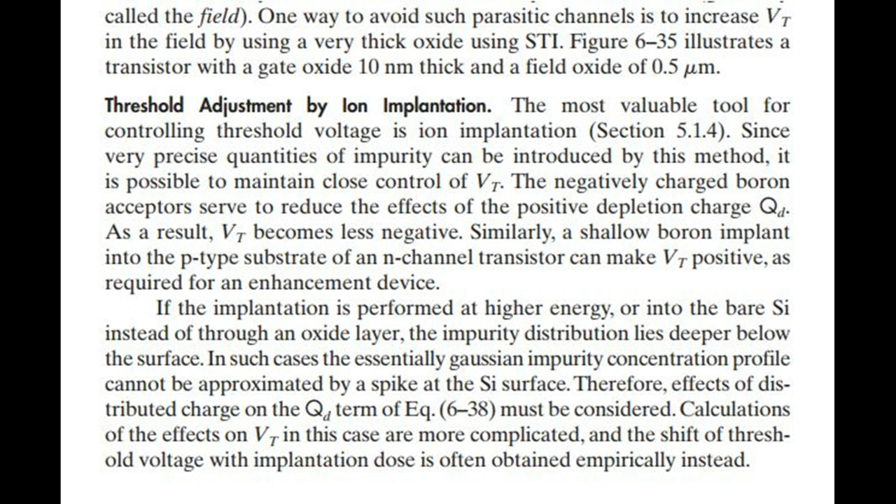In such cases, the essentially Gaussian impurity concentration profile cannot be approximated by a spike at the Si surface. Therefore, effects of distributed charge on the QD term of EQ 638 must be considered. Calculations of the effects on threshold voltage in this case are more complicated, and the shift of threshold voltage with implantation dose is often obtained empirically instead.